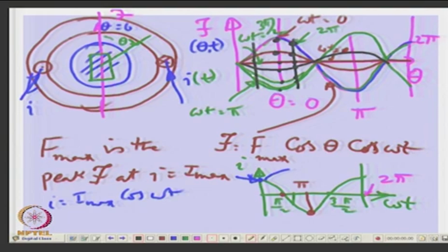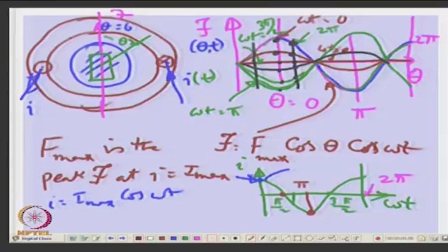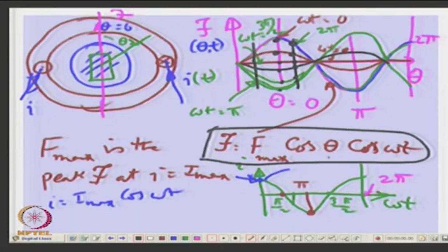Is it clear? Any doubt? So, obviously, you are having a magnet whose strength is changing with time, but the axis is not changing. Okay. So, peak value will be there, but at every position of the air gap, it will have a different potential at different instants of time, which we would always say means the air gap MMF is a function of space and function of time.